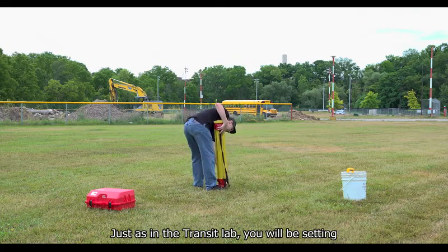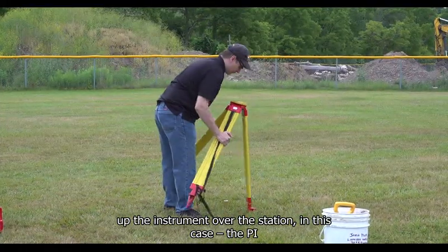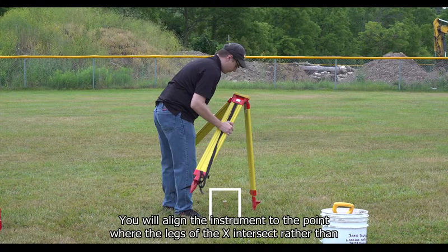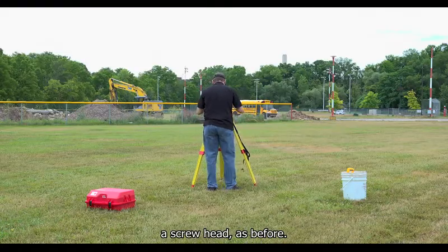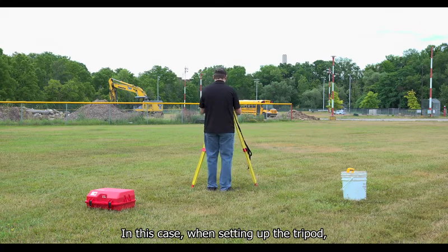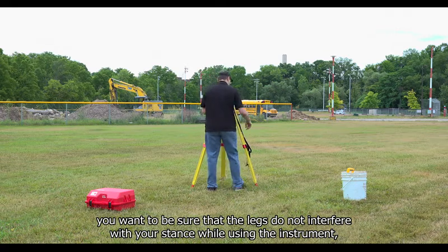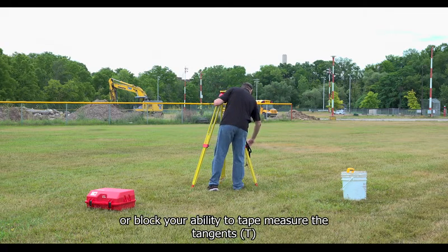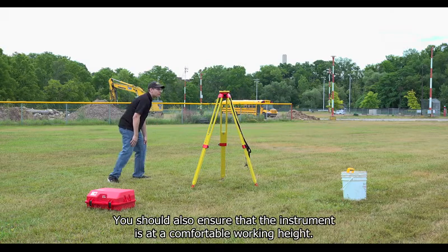Just as in the transit lab, you will be setting up the instrument over the station, in this case, the PI. You will align the instrument to the point where the legs of the X intersect, rather than a screw head as before. When setting up the tripod, be sure that the legs do not interfere with your stance while using the instrument, or block your ability to tape measure the tangents. You should also ensure that the instrument is at a comfortable working height.